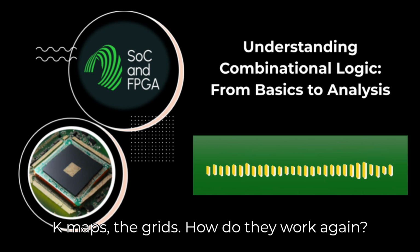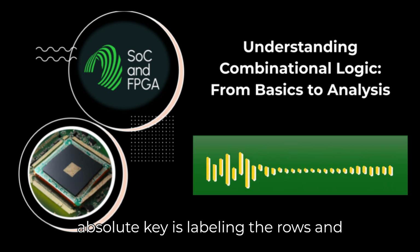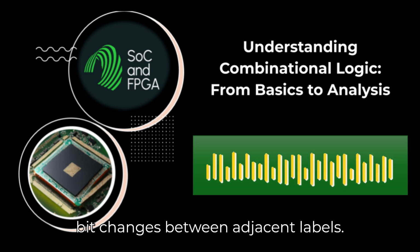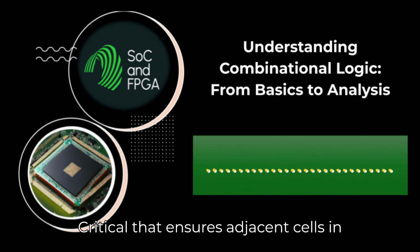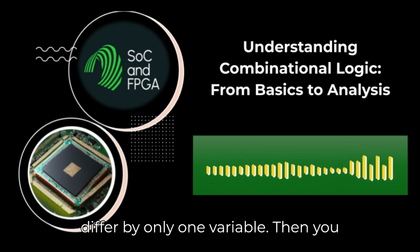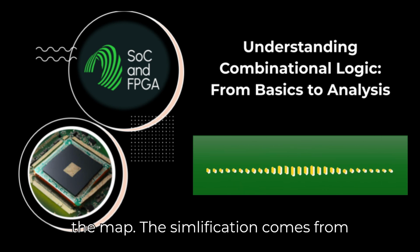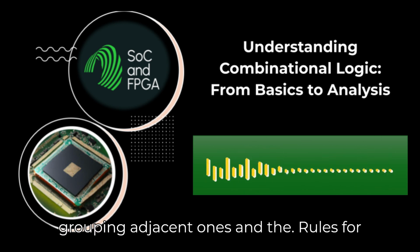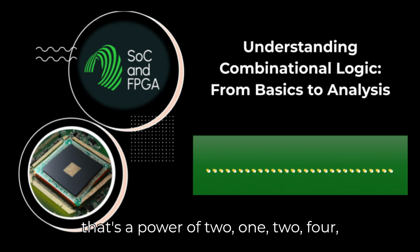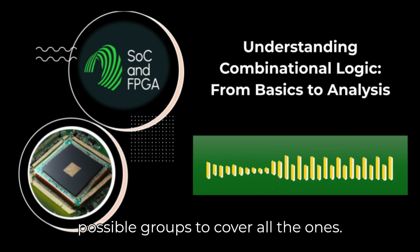The grids, how do they work again? You create a grid with 2^n cells. The absolute key is labeling the rows and columns using Gray code, where only one bit changes between adjacent labels. Critical. That ensures adjacent cells in the map represent input combinations that differ by only one variable. Then, you plot the ones from your truth table onto the map. The simplification comes from grouping adjacent ones. And the rules for grouping? Groups must be rectangular. They must contain a number of cells that's a power of 2: 1, 2, 4, 8, etc. You aim for the largest possible groups to cover all the ones.